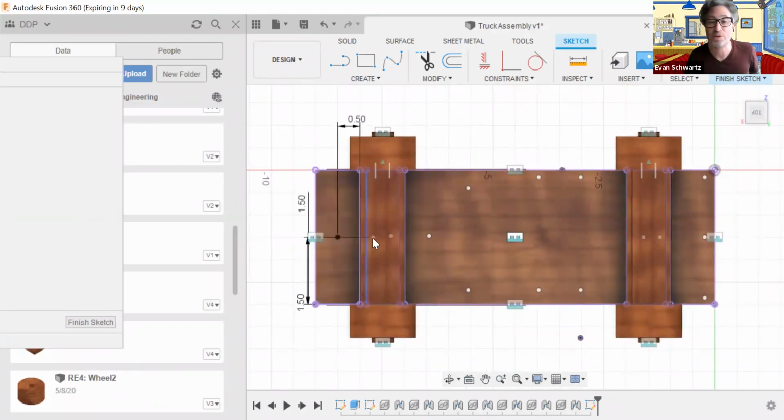All right. So we have dimensioned this one, but we haven't fully dimensioned it because it's still white. So I'm going to go back to my dimensioning tool, and I've so far only dimensioned these 2 points one time. So that is going to be 1.5. Okay, now we needed the right distance between here and this side. All right, and for that, I am getting a 0.075.